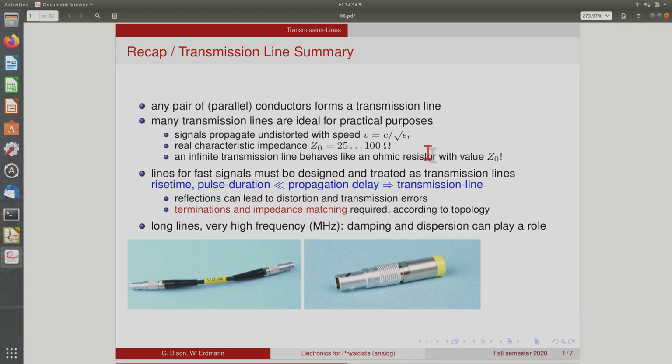And when you use these LEMO cables, for instance, which we often have in the laboratories, they have a small label with the transmission time. So this one is a 0.5 nanosecond cable. The other thing you often use will be these little 50 ohm resistors that you can plug into a cable to terminate it. So usually when you work with transmission lines in the laboratory, you have a box of these things lying around somewhere.